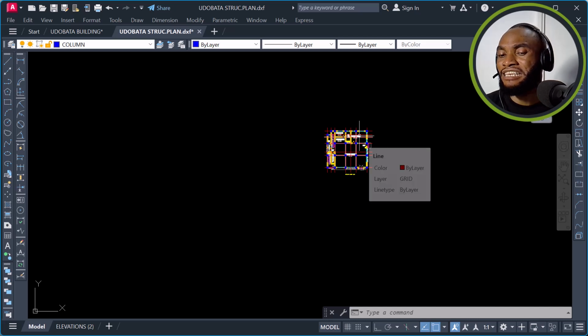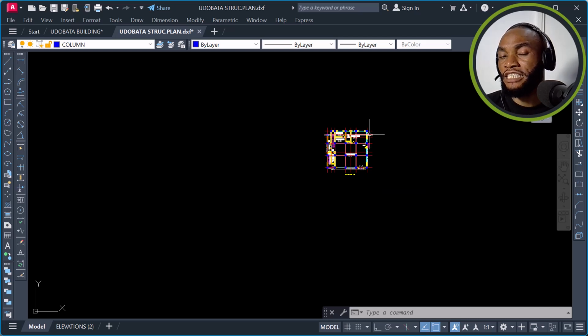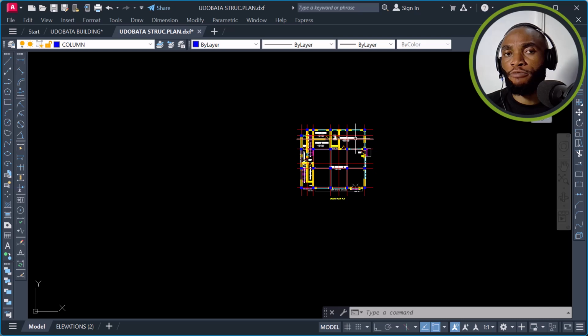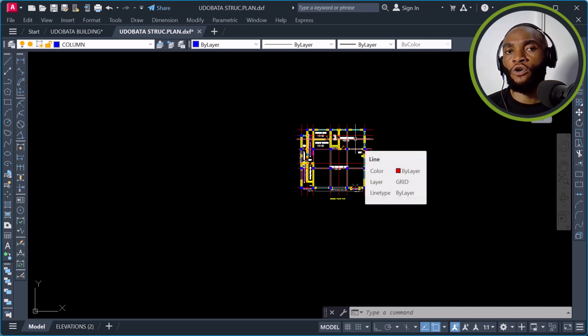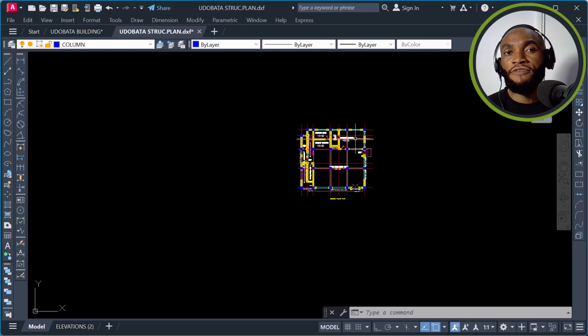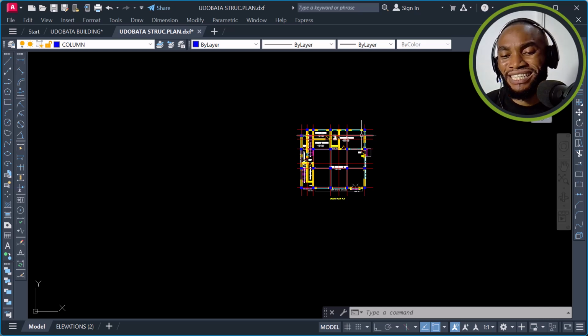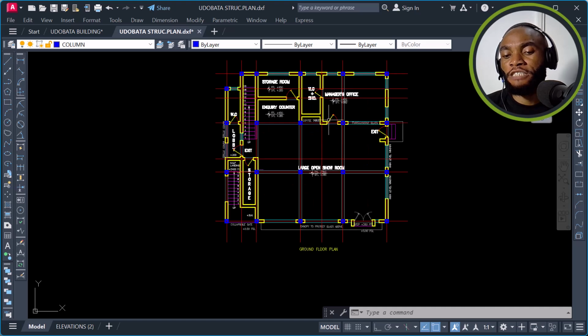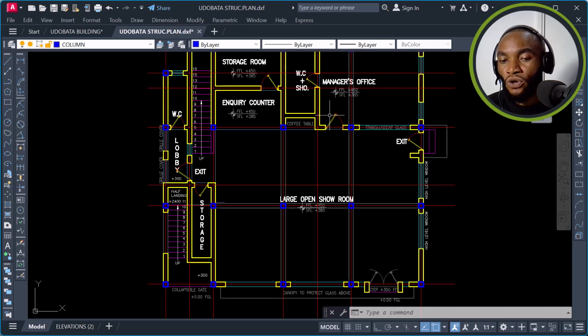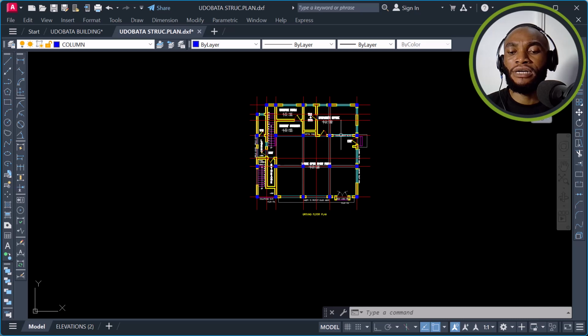Now, there is a reason for that. If you don't learn it, you might export a small building plan to 2022 version of Protastructure and above, and it will appear well. But when you are dealing with a massive structure, a massive building plan, you will see that if you don't put it on 00 coordinates, you'll be having issues on your design. Okay, that's fine. So I'll have to put this plan on 00 coordinates. And how do I do that right now?